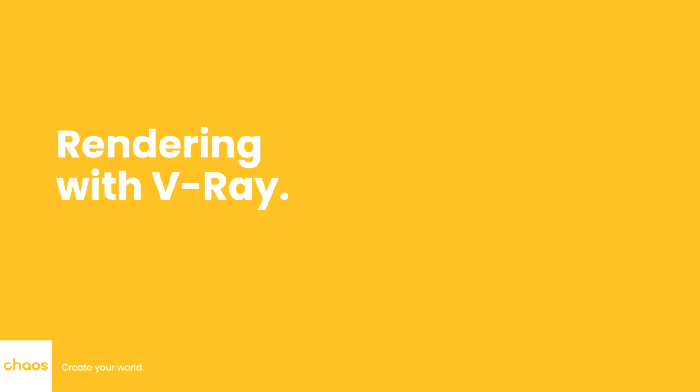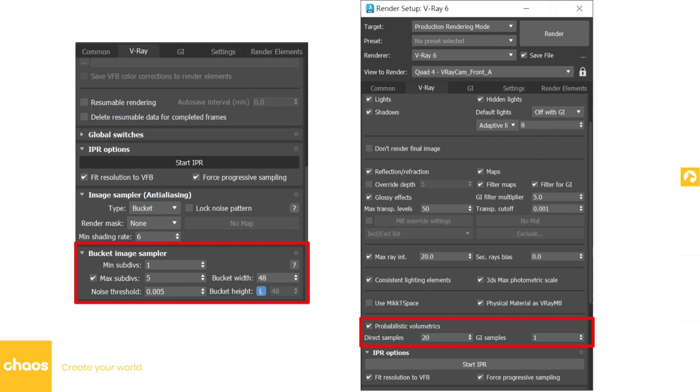Finally, we have reached the last stage of the process. To improve rendering performance, I made two changes in V-Ray. I adjusted the max subdivisions of the image sampler and the probabilistic volumetrics. By lowering these values, I reduced rendering time while still maintaining acceptable image quality. The default value for the direct sample is set to 20. You can experiment by lowering this value to 15, 5, 3, or even 1 to find the optimal value. Note that this value may vary across different scenes.